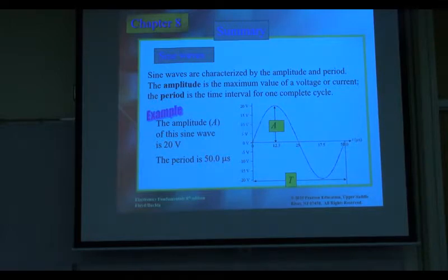Okay, now we can imagine if we know the period T, the T in this example equals 50 microseconds, and we want to know the frequency F, how do we get that? What's the relationship between the frequency and the period? How do we get 20K in this example? You use 1 minus the T, right? Sorry, 1 divided by the T. Mistake. So 1 divided by the T, right? Yes, so that is the correct formula.